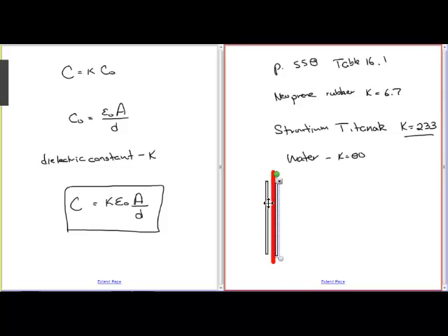I put that right up against the red thing, and I put that right up against the red thing. So not only does this material inside increase the capacitance because of the dielectric constant, but it allows me to make D very thin, small. It's kind of like a spacer as well. And as long as the voltage across the capacitor is not too large, this barrier will prove effective. Now, if you put too high a voltage, it's going to arc through the material and it'll destroy the capacitor.